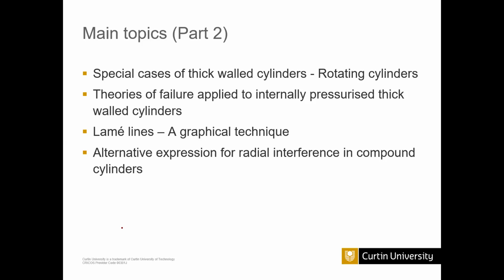If you remember, to find the stresses on an inclined plane, we already derived the equations and can use them. There is also a graphical technique, Mohr's circle, with which we can find the pressures or stresses. Then there are Lamé's lines and alternative expressions for the radial interference in a compound cylinder.